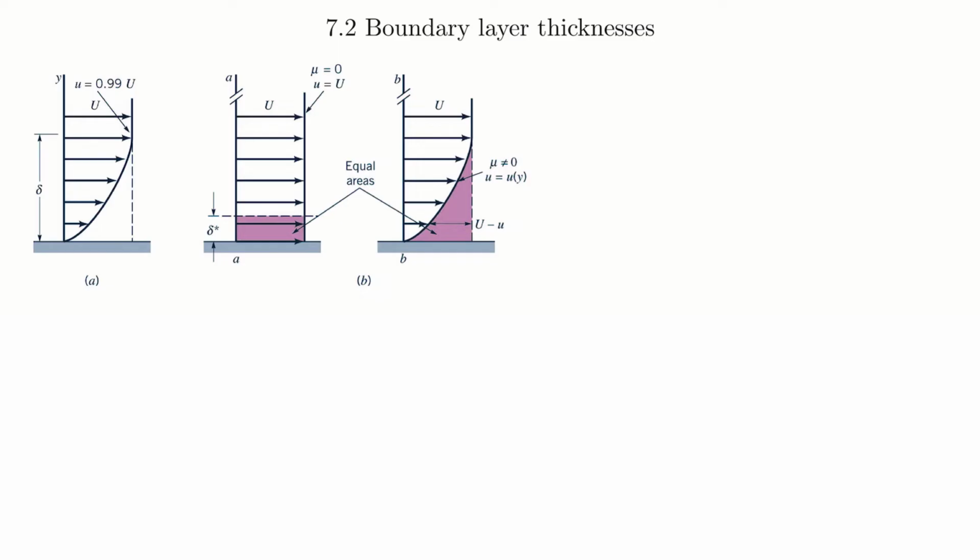We have multiple ways of describing the boundary layer thickness. The first one shown in A there, this delta, is what we call the disturbance thickness. That's defined in a way that's easy to understand, but very challenging to really measure or use in practice. Lowercase u is the local velocity, and you say the point at which that's 99% of your free stream velocity, capital U, the velocity far away from the surface.